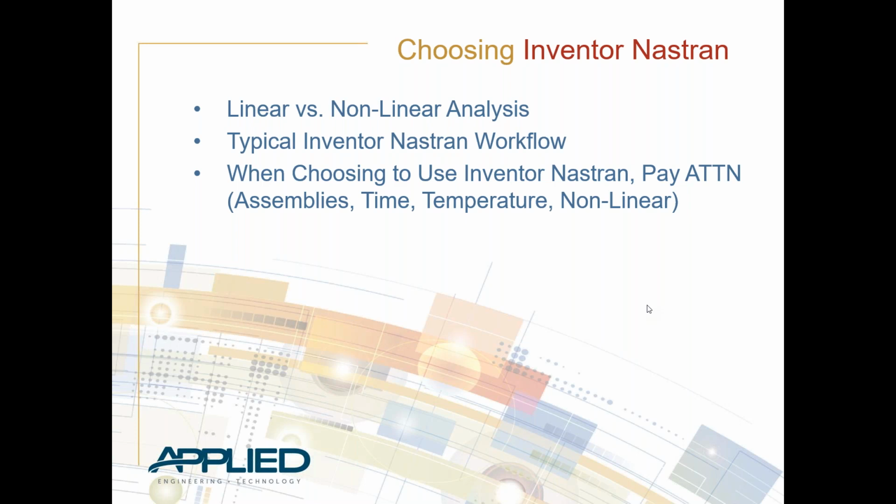The nice part of it is you can go back and forth between your Inventor model, run an analysis, and if you see something that needs to be tweaked, go back. You don't have to leave the system or copy the file or create a dummy solid from it or something like that. We can go right back and forth within the same environment, make those changes to the model, and then run the analysis again.